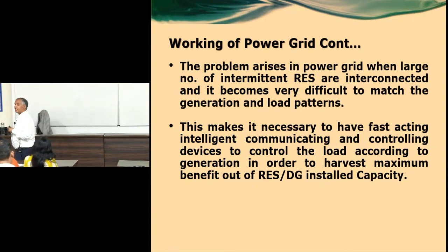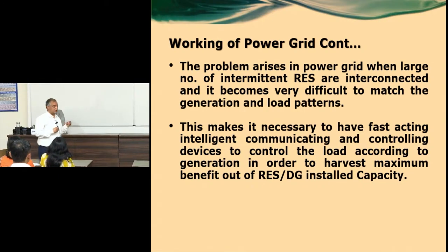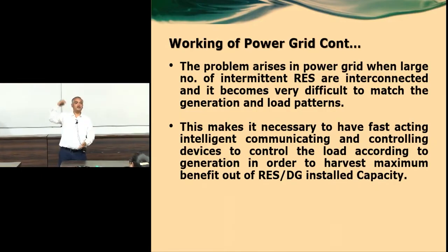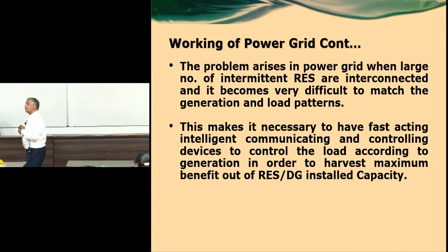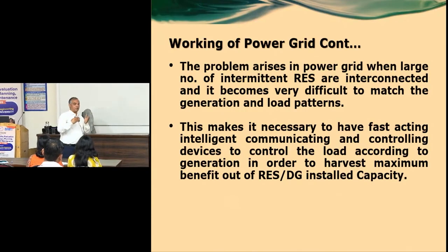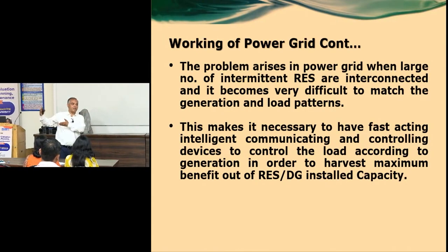So the issue is arising that the solar power developers or wind power developers have to install big reactors to absorb that capacitive reactive power. So that is also becoming a challenge. Evacuating power from a gigawatt-size wind turbine or solar power plant is not that easy, because they are being generated at light load centers, and the Ferranti effect voltage is already high, and you are further generating at that point. So again it is going to be very high.